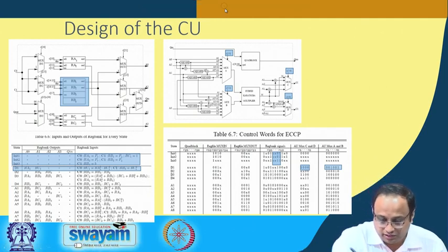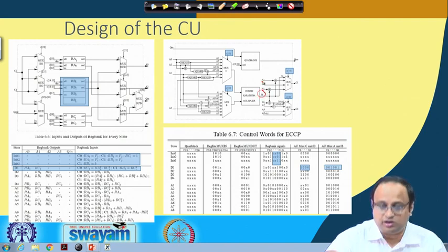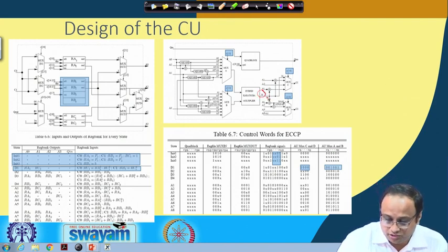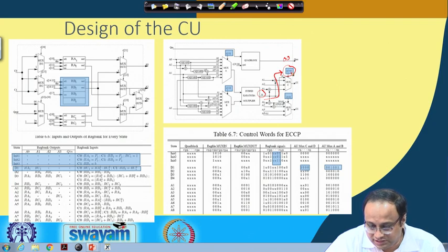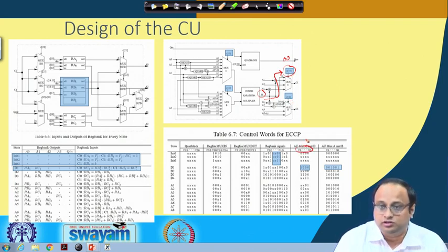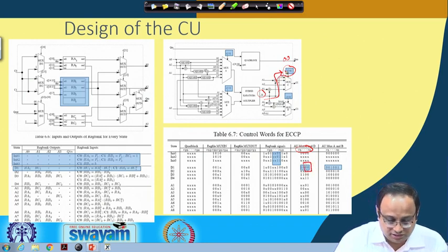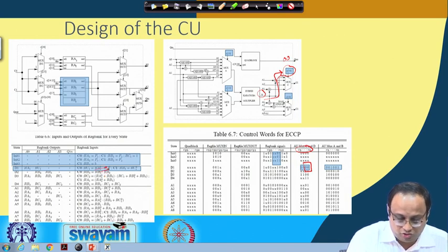This is your final result where you are getting the output. This output needs to be multiplexed out, so this select line should be set to 0 0 at that point, and that is precisely what is done here. C6, C7, C8 and C9 are the corresponding control logic. These 2 bits are 0 0 here, which means that the multiplier output is getting passed, and it is passed out on the C0 bus.